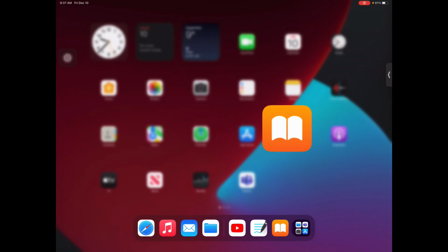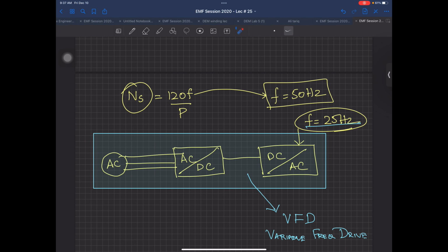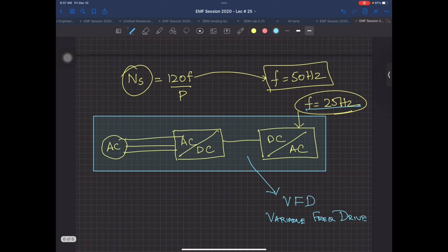So if I go back to your lecture, when we are talking about the speed control methods, if I name them, one is the frequency, very, very important. Your frequency is the most important factor with which you can actually change your speed. But remember, a variable frequency drive which has the option of changing the frequency and the voltage also is better suited for your device. There are some in the market, maybe Chinese or some local production, which only change the frequency, they don't change the voltage.